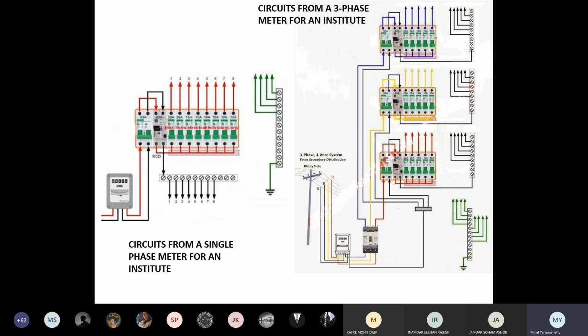So that is the distributional difference in an institutional building when one payer is there and when multiple payers are there. What happens is the line comes in, it first gets distributed via the bus bar, and each individual line goes to the meter, but before the metering happens, you have the cutout. Once the cutout is set, it enters the meter of 41, where 10 will be the commercial meters and the rest will be residential meters. From there, there will again be one fuse, because this fuse is protecting the line which is coming from the meter to the individual flat, flat number 101, 102.